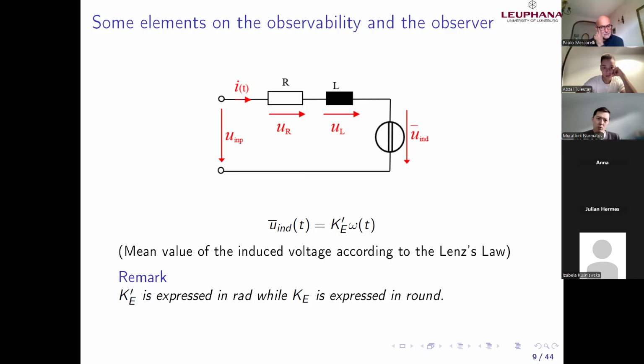differential equations. Yeah, this equation here is the induced voltage. We can see it localized here. Believe me, it's not the topic now to understand this actuator, but we can see that this induced voltage is a reaction with respect to the movement. I mean, moving the rotor inside the electrical field, we generate a voltage which works against the current which is generated by the voltage input.